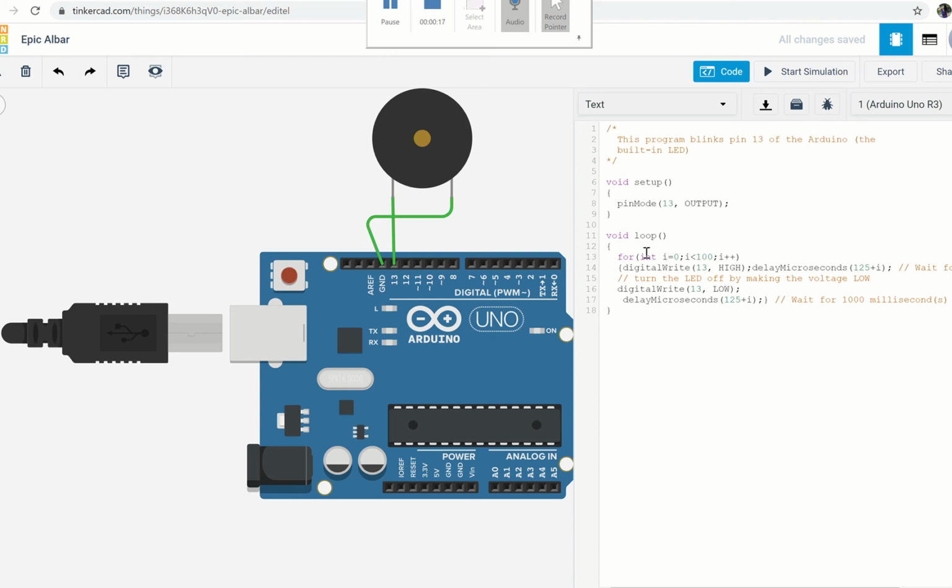In the previous video on Piezospeaker, we understood that the sound frequency is basically controlled by the square wave of the voltage signal. If we can control how long each half cycle will be on high and how long it will be on low, then we can control the frequency of the sound. Knowing that basic, to create an alarm sound you want it to have different frequencies, and that frequency change is continuous.